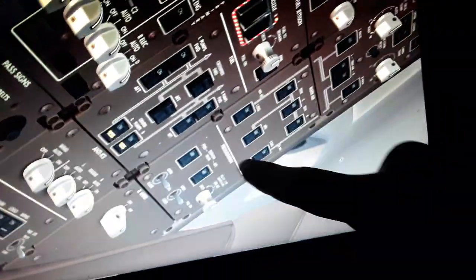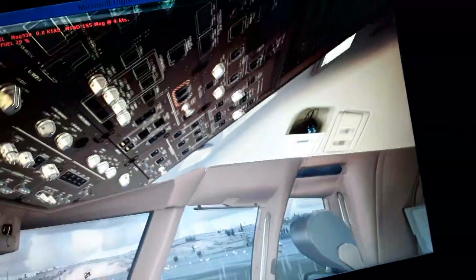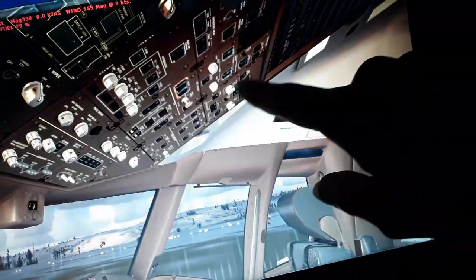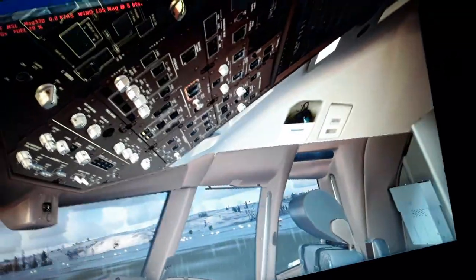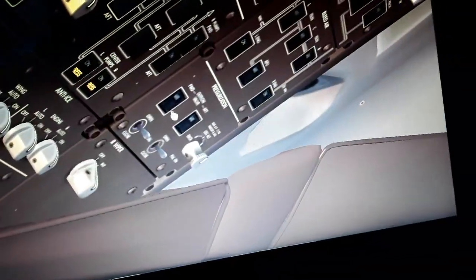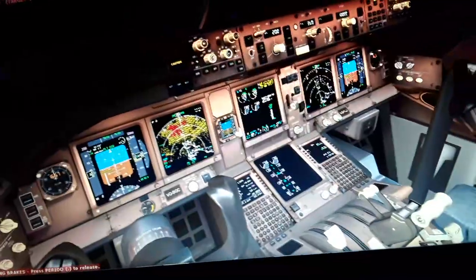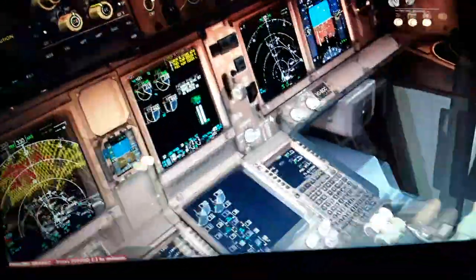The wing and engine anti-ice, the cabin pressurization system here, valves, also the bleed air pressurization we need from the APU to start the engines, also bleed air from the left and the right engine for hydraulic fluid pressurization, cabin pressurization, wing and engine anti-ice, air conditioning and ventilation of the aircraft. So we're gonna use all these switches here on. You will see what happens. Then we're going to use the manual for the cabin pressurization. So you see the outflow valves here on